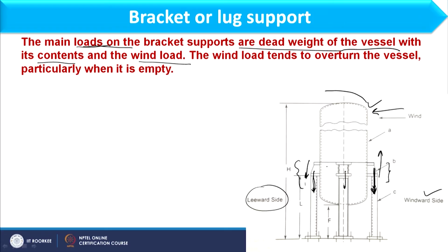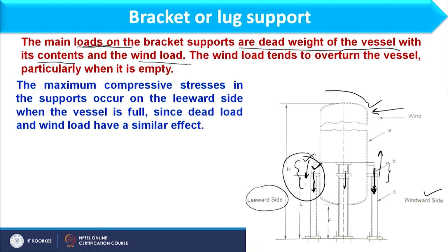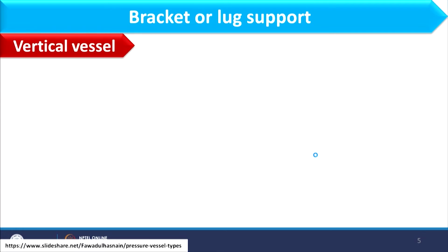So, as far as load is concerned, this would be the extreme condition for the support to bear, and therefore, for design purposes also, we will consider this condition where load due to wind and load due to dead weight will be considered together. So, let us start the design of bracket or lug support.